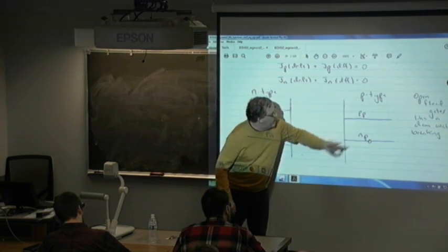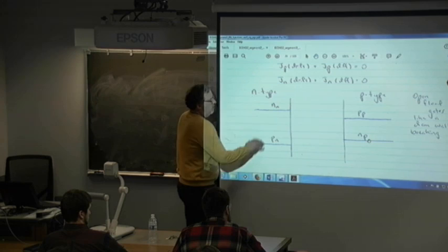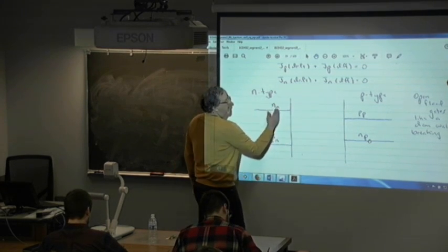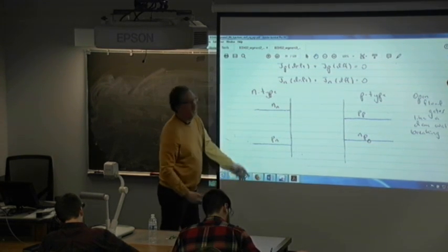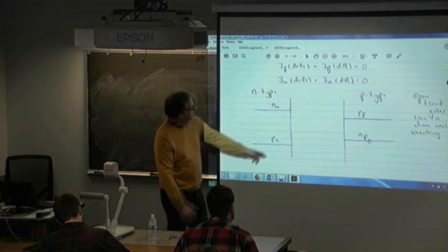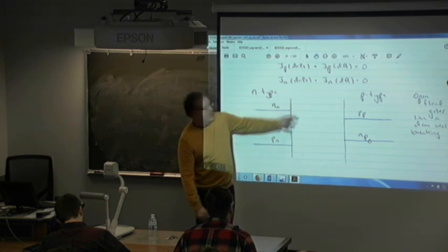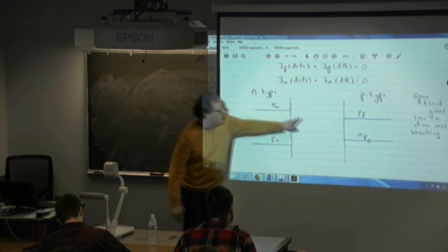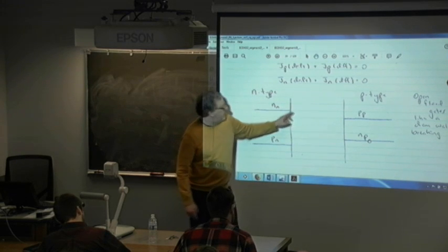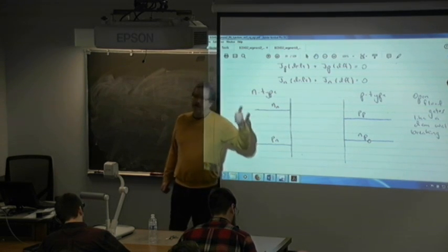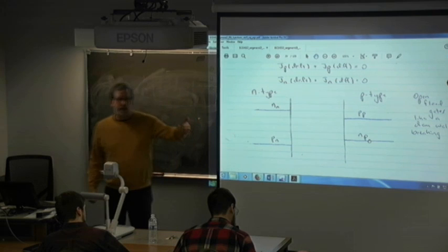And we have the minority carrier electrons. So the electron density, and remember, in the way it's graphed in the textbooks, this is the semi-log. So this is many orders of magnitude difference, and so that means we have a concentration gradient.